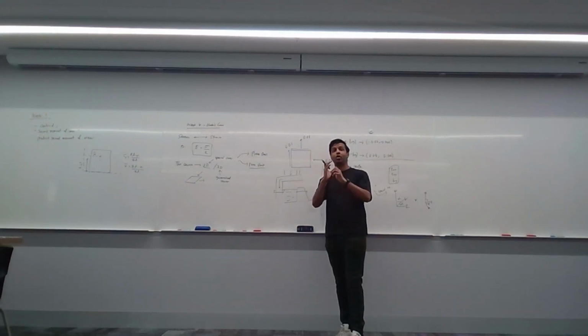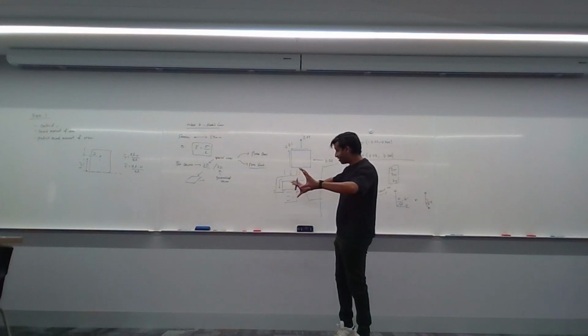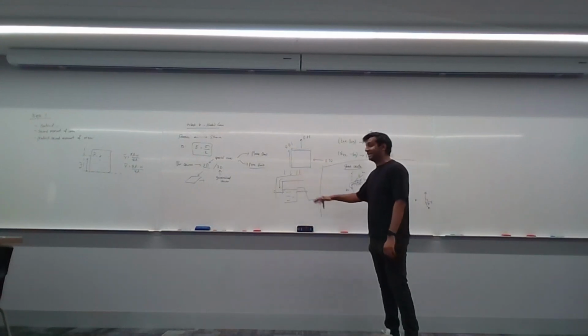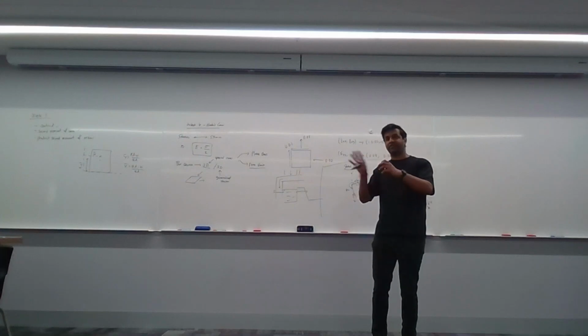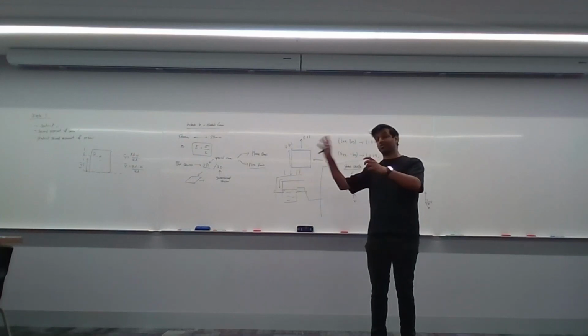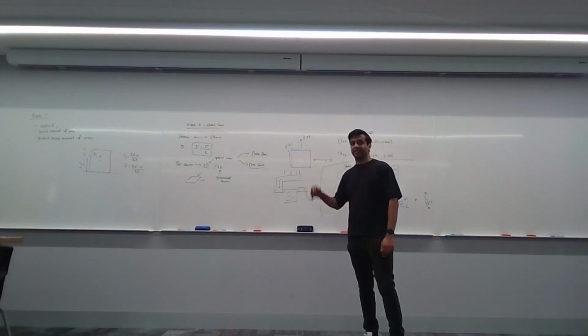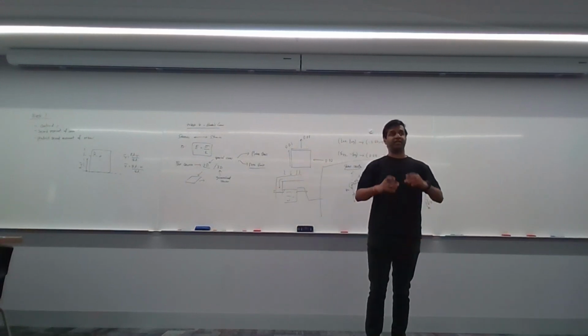Why? Because it's a lot stiffer into the page than this way, because it's got a very, very long distance into the page. So any structure that has one of its dimensions much longer than the other, most likely would be in a plane strain case.